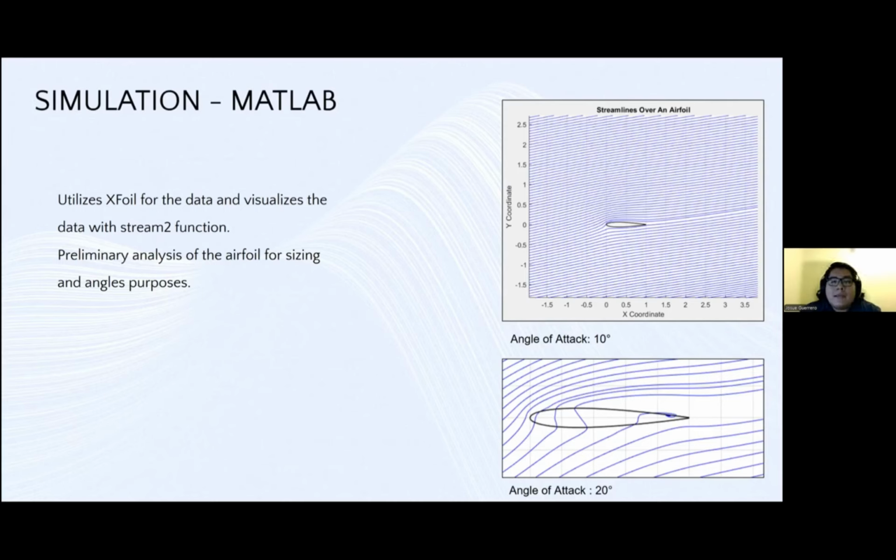Lastly, the blockage effect, in which the stream closest to the test object is accelerated due to compression, is a concern within the wind tunnel, so appropriate sizing is necessary to minimize this effect as best as possible. This can be approximated visually through the simulated streamlines, where you look for the general point at which the streamlines are mostly unaffected and closely resemble the free stream, or alternatively, it can be calculated through the comparison of velocity components. I'll pass it on to Yonghao for Xfoil.